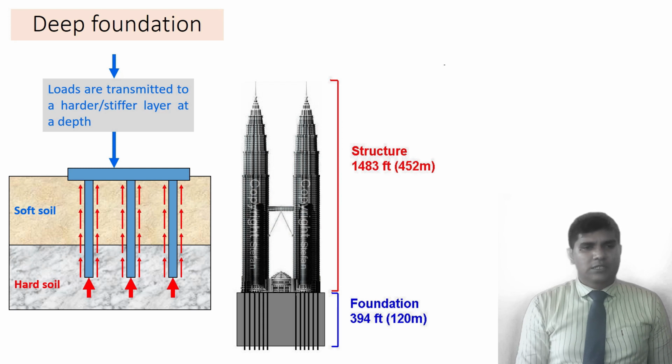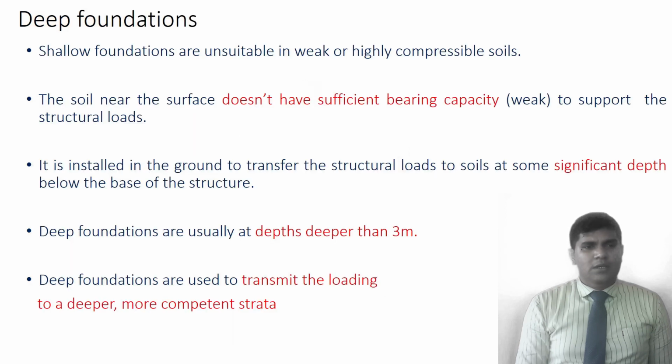Therefore, we go with piles and transfer the load to firm soil or bedrock. In the deep foundation concept, commonly the depth is more than 3 meters.